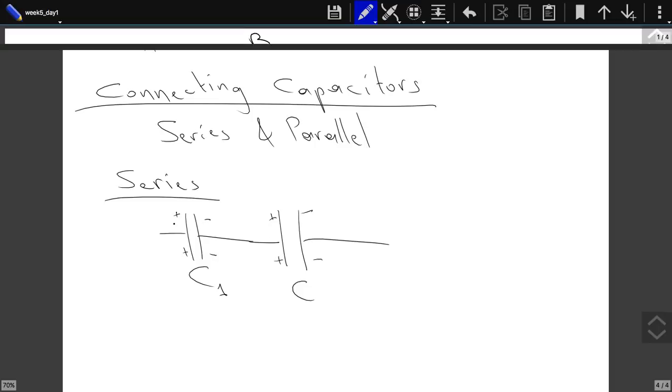So let's say we put a charge Q in this capacitor. That means on the positive plate we deposited plus Q. On the negative plate we deposited minus Q. So here we have a plus Q charge on this plate and a minus Q charge on this plate. So the first thing, how much charge did we store in this capacitor? Let me put it in a different way. When we say that we store a charge Q in the capacitor, we basically take plus Q from one plate and put it on the other one. That is just the amount of charge we stored. We moved it from one part to the other one.